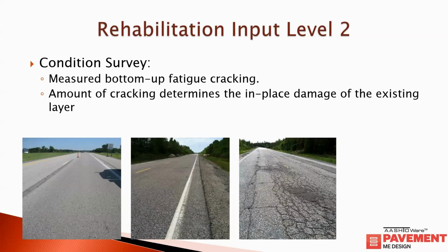What you want to enter is to try and separate out the percentage of how much is actually top down versus bottom up, and that can typically be figured out through coring at the crack, or estimating the damage based on what you're seeing on your roadway.